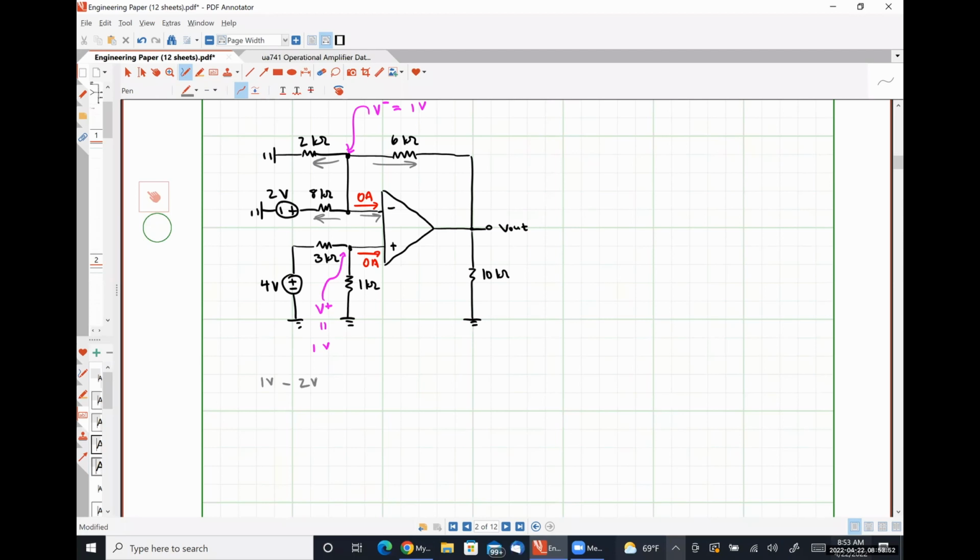So that's giving us the voltage drop over the 8 kilo ohm resistor divided by 8 kiloohms. Nothing different than how we would write our KCL equation when we were applying nodal analysis. The voltage at the node we start from minus the voltage at the node we end at divided by the resistor value itself, okay? The current flowing in the bottom right is obviously 0 amps because we've already written it there, so let's move past that one.